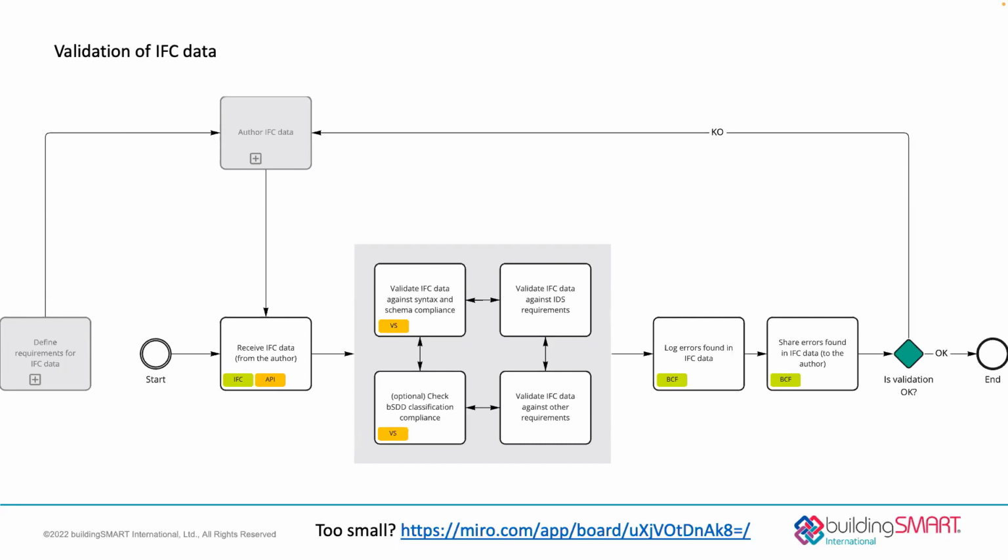So when you set category 21, 22 wall, it's still up to you to make sure that it's external and load bearing? But when you use the VSD, we have examples. There's a very nice demo, we have a movie as well, in SketchUp. SketchUp has a plugin where, when you search in the NLSP and double click 21, 22, it adds the classification reference, but it also adds the properties and the values to the file. The idea is that it would help users to do that. So we hope, we expect software tools that support VSD for end users to implement that. It's not only adding the properties and the values, but also the references, the URIs as well.